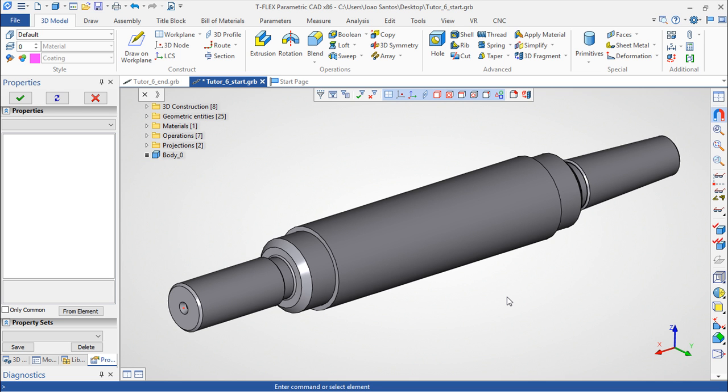study, we need to have two different steps. The first one is required to examine the effect of the static loading on the given workpiece or structure. In this particular case, it's only one part. So we need to perform a static analysis. And this is required in order to find out whether the workpiece is damaged under the action of the given loads.